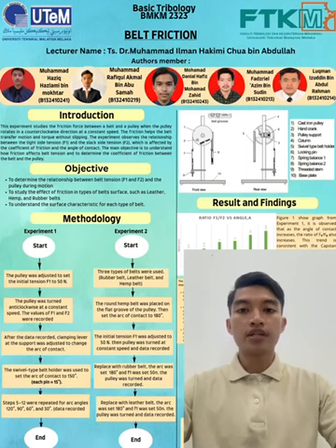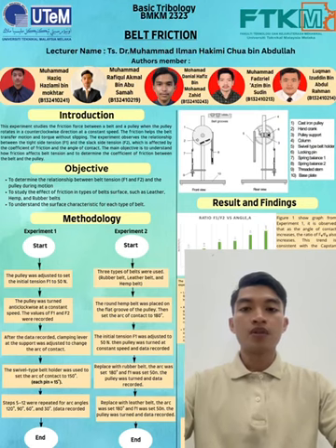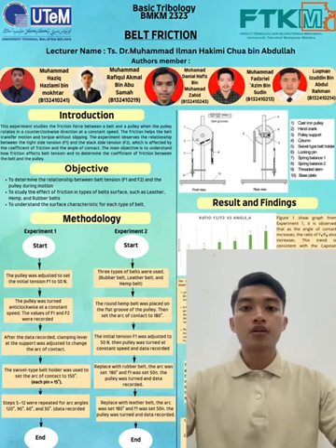The pulley was adjusted to set the initial tension F1 to 50 Newton. The pulley was rotated in anti-clockwise direction at constant speed, and then the values F1 and F2 were recorded. After the initial data were collected, the clamping lever and the support were adjusted to change the angle of contact. A swivel type belt holder was adjusted to set the desired contact angle, where each pin interval represents 15 degrees.